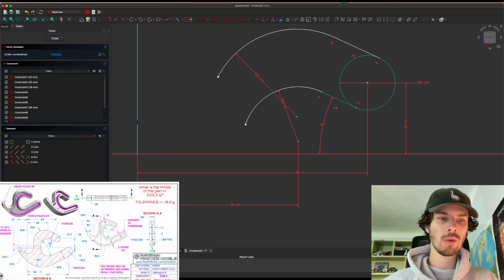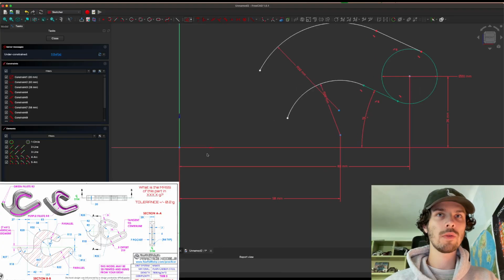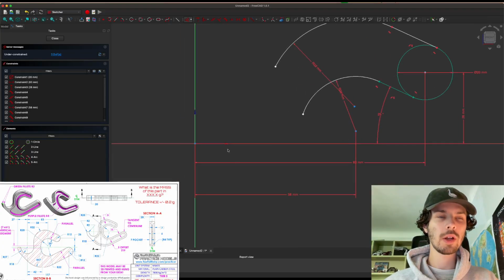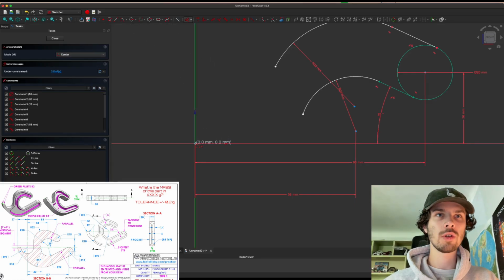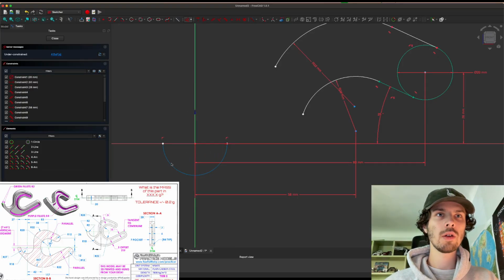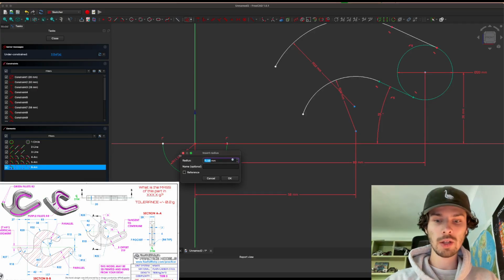So now I'll move in on the left side of the shape and add two of those radiuses. So again, the create arc by center. I start from the middle, go to the right side, twist it up, 180, add dimension to it. So this first one is 18.